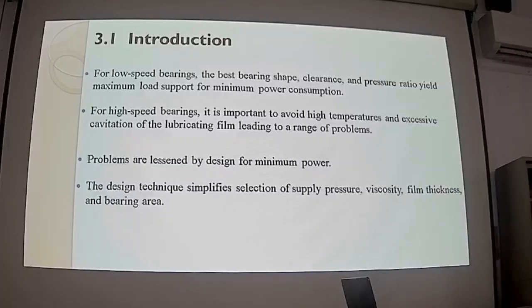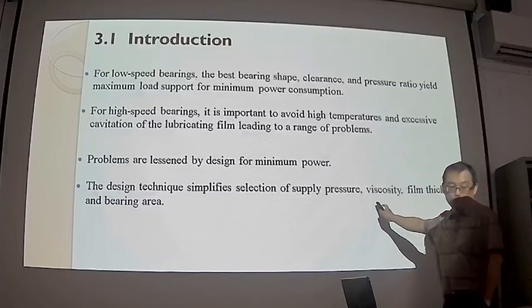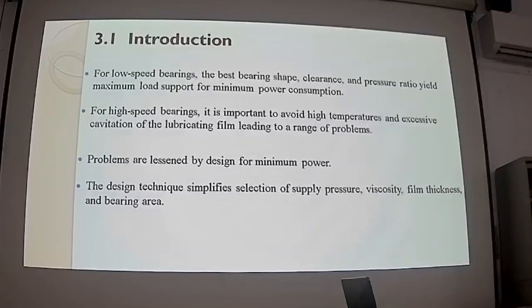So there are some design guidelines, rules of thumb, to decide what is the viscosity and what is the film thickness. We can talk about it right now. For the viscosity of the hydrostatic bearing, it is usually decided by the rotational speed, the maximum rotational speed for your hydrostatic bearing.